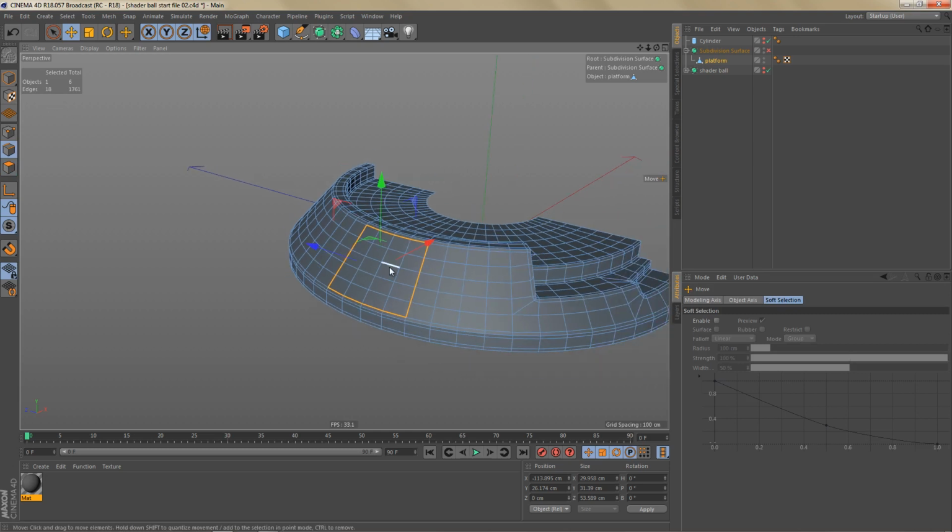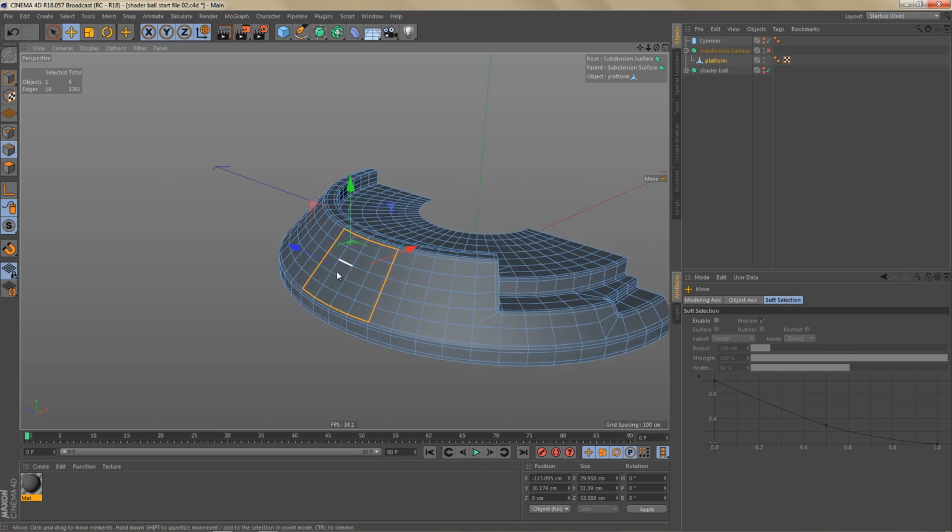Now that is a bit of a bummer because my original idea was to create a cylinder and to combine the cylinder with half a sphere. The problem is that the segments a sphere will give us will always be divisible by 4. And that means I can get either 16 edges or 20, but not 18. So how do we solve this problem?